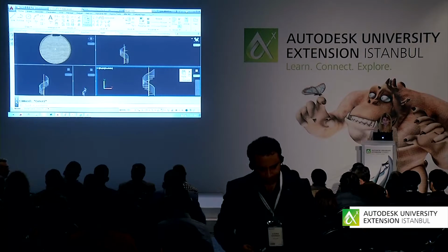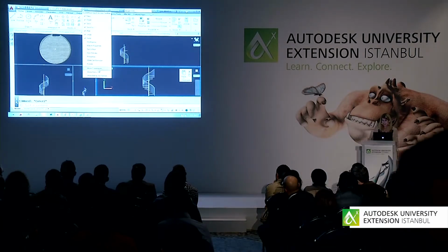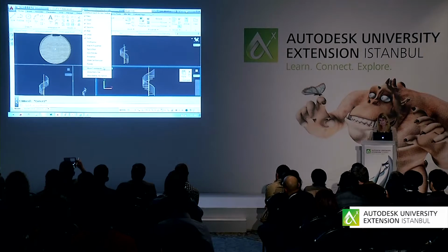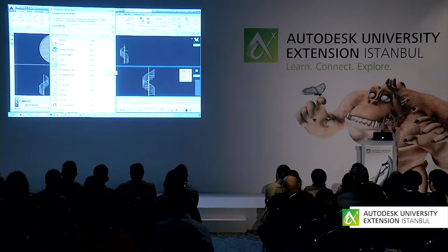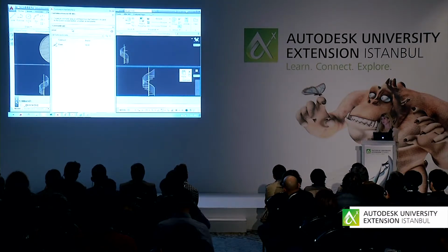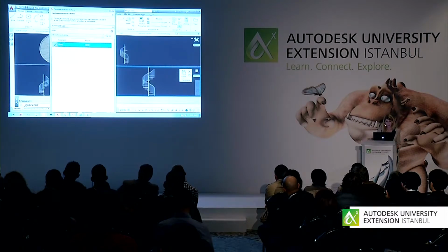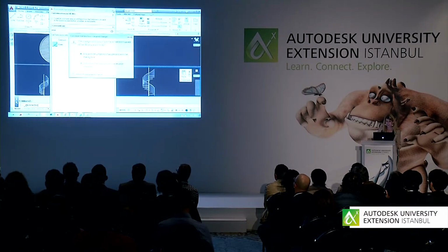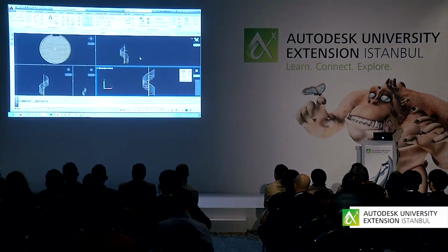Okay. You can also say Add More commands, and it will take you into an abbreviated version of the CUI. You can type any command that you want, and you can put that on the Quick Access toolbar. And this has been valid since AutoCAD 2009, so none of this is specific to 2014. So I can grab Erase, I can drag and drop it up in the Quick Access toolbar, and I won't be able, because of the resolution of the screen, to select at the bottom. You can see it's off the screen, so it's going to call me names, but that's okay. All right.